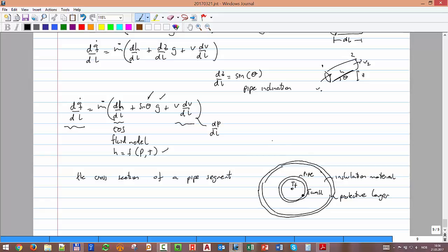And then we have just the C. Okay, C. And then we have here some temperature, that is temperature ambient. And there will be heat transfer between the fluid and the ambient through all of those layers. And the equivalent, if you think about electricity, is that this T is like a voltage difference, and you have some current going through it, and the current will depend on the resistance. The current is like the heat flow, and the resistance is all these layers you have in between.